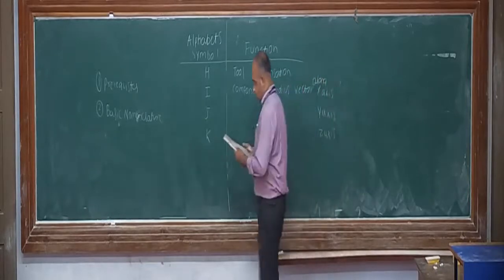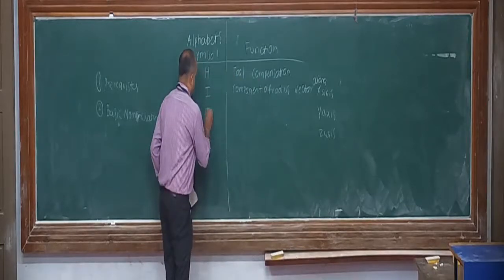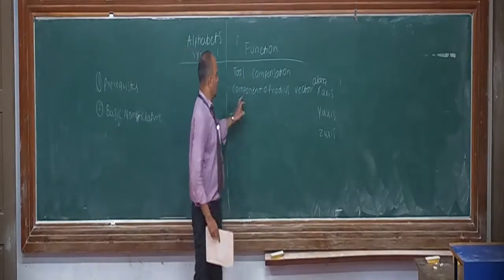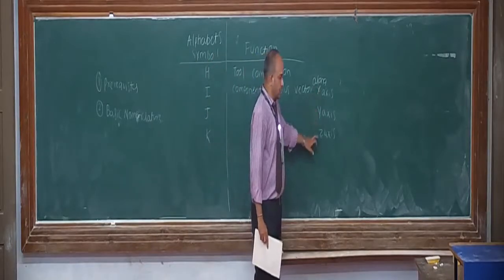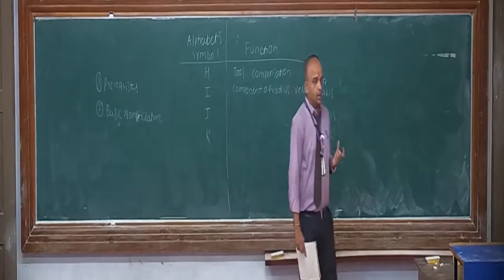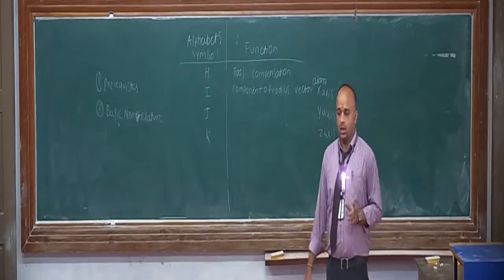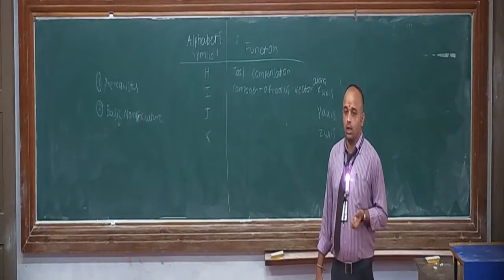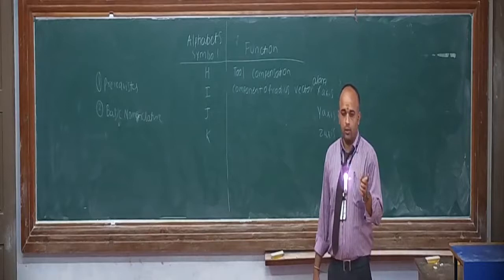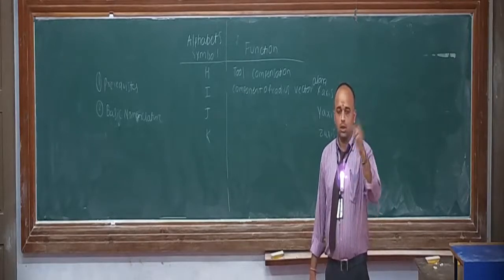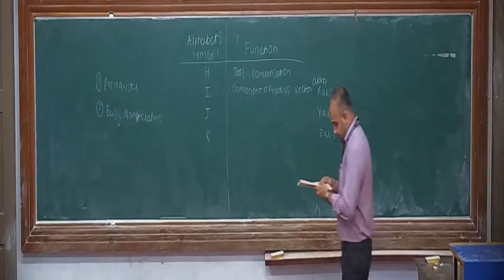So here, I, J, and K have the standard meaning. This is the component of a radius vector along the x-axis, y-axis, and z-axis. What is the meaning of this and how is it utilized in CNC programming? That we will understand when we use the concept of interpolation. During interpolation, when we are writing a program which has a contour or a circular rotation, at that time we will be using this I, J, and K.